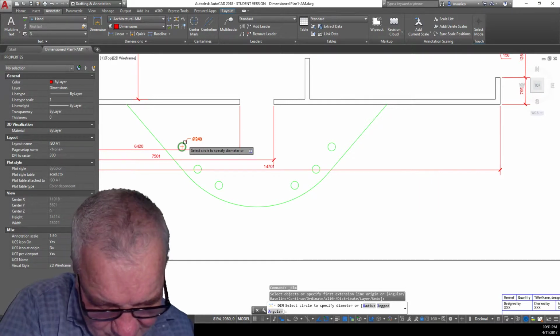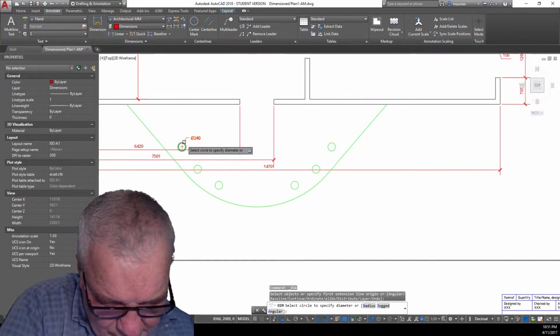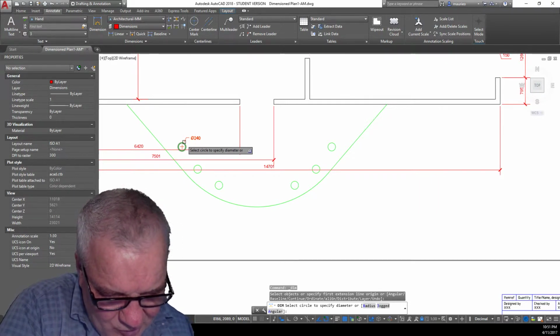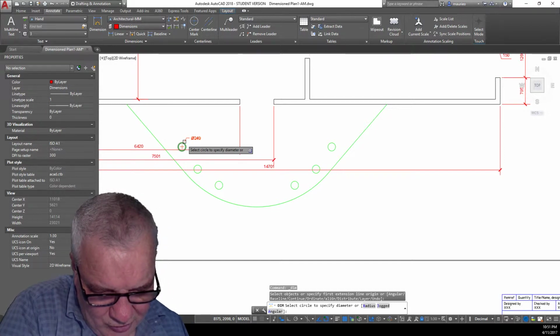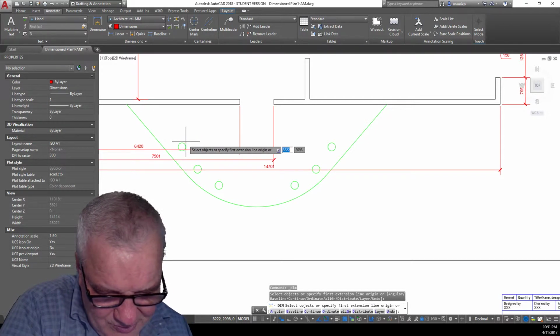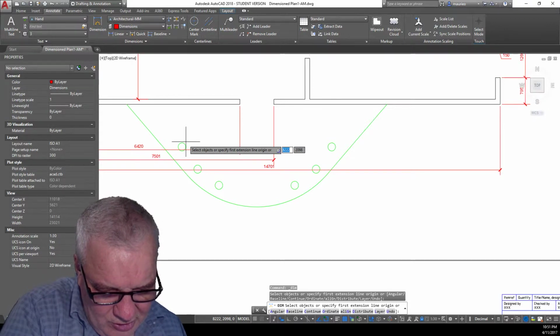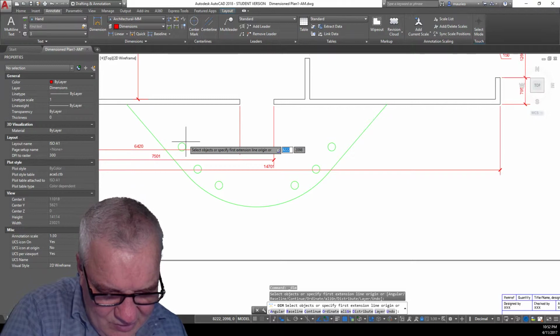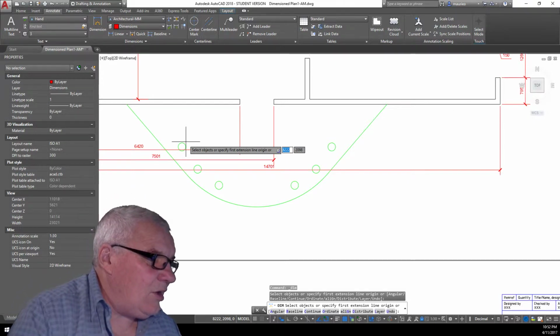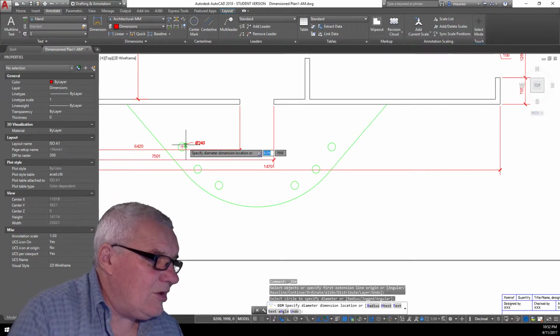It definitely says here, hover over one of the 6 circle columns. If the cursor does not display the diameter dimension while hovering, toggle off object snap in the status bar. Select the circle to accept the diameter dimension and click again to place it at the required location.